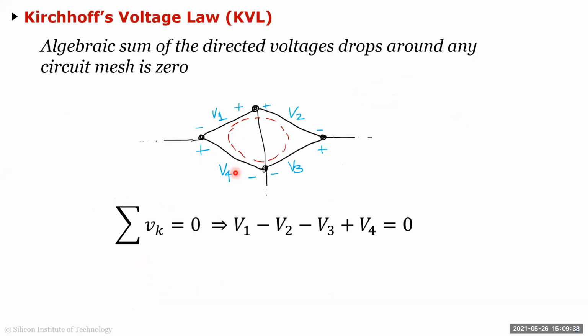Then that will get satisfied. And in our circuit that is usually the case, because the time varying current going around in the loop is typically so slowly varying compared to the dimension of the circuit that you don't have any huge change of electric field. So then this always holds. If that's not the case, like in RF, for example, if you have a big circulating current like 10 gigahertz, this is not true, because this will be equal to whatever is the change in electric field inside it.